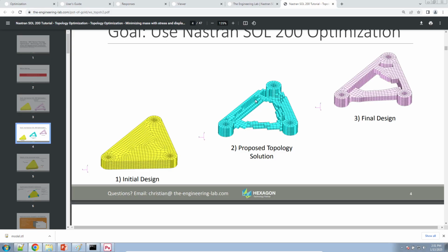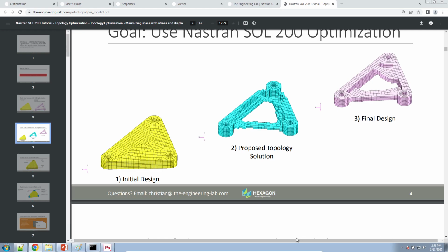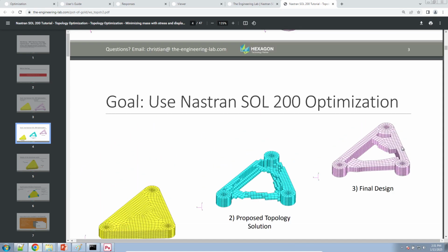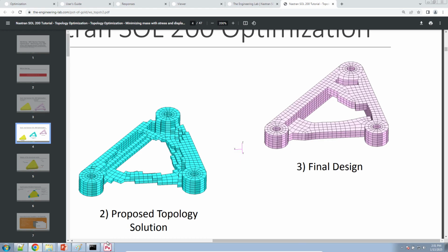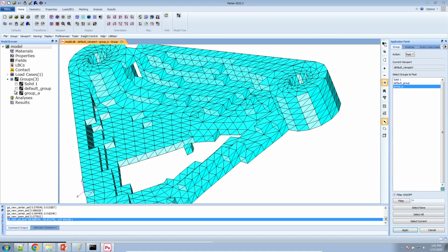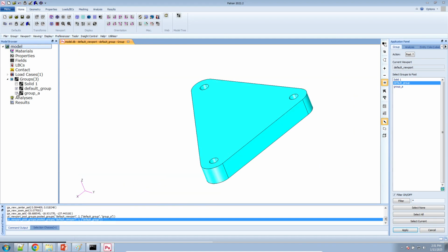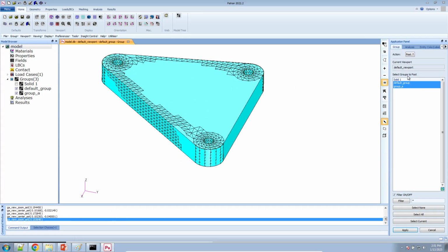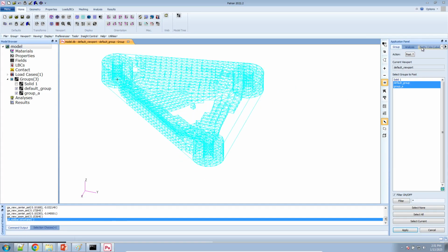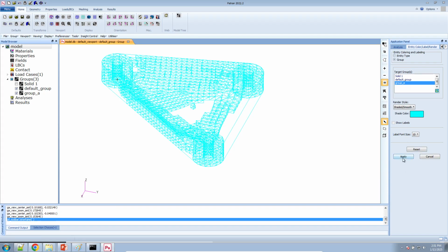The mesh has lingering elements. The mesh is not smooth. You cannot use this mesh for anything. What you do is you go into CAD, you superimpose your original CAD with the STL file, and you use that to help remove material.